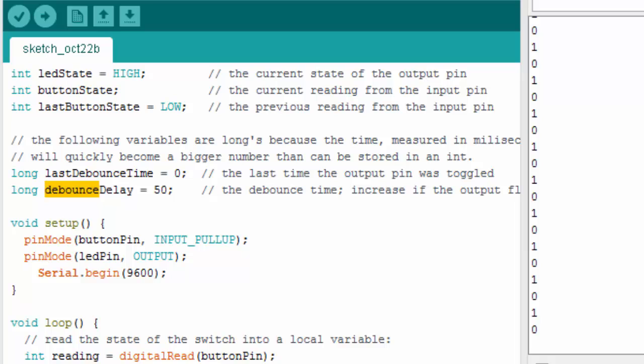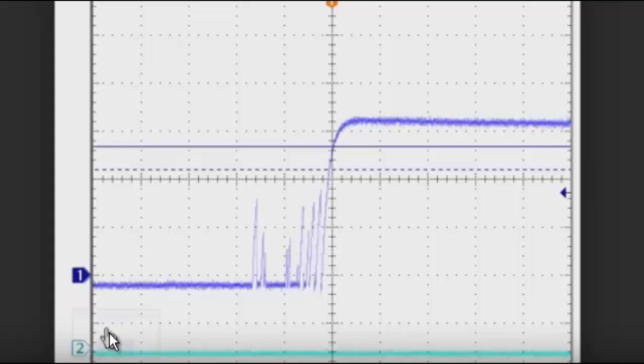And in the second example, how to build an on and off switch, we have to take care with debouncing. And debouncing is, you saw how fast the Arduino was cycling, and those lines are cycles. The Arduino is reading, and it reads low, low, low, low, low, and then here in this cycle it's not low and it's not high, and that can be some noise, like a cell phone is too close to the wire, or probably you're touching the wires or whatever.